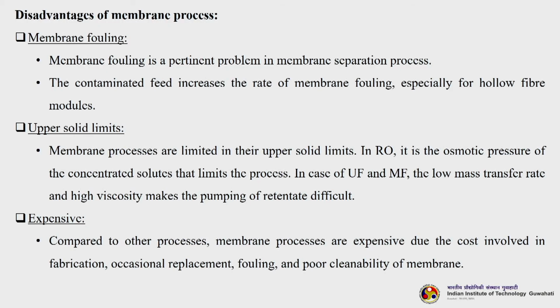So, in case of ultrafiltration and microfiltration, the low mass transfer rate and high viscosity make the pumping of the retentate difficult. So, if you have a very highly viscous solvent, which is our retentate, then taking it out, so basically pumping it out from the membrane module or the membrane reactor system becomes a bit difficult and challenging.